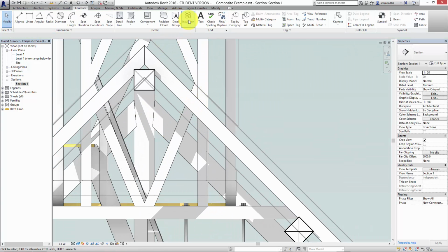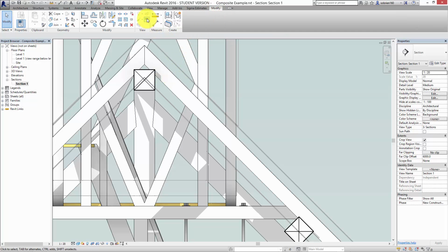And the other thing we can do, which is very useful, is we can use this modify. And there's another shortcut that's really good to know here called LW. It stands for line work, because the model doesn't necessarily generate the correct line work as you want to have it graphically within your drawing. So if you press line work here, it gives us the option.